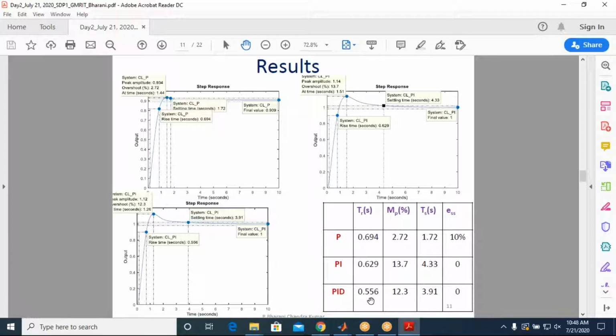When you use the integral action, it sometimes saturates. It gives saturation in the control gain or in the system's response as well. To avoid that saturation, we generally use the anti wind up controller. So anti wind up will avoid the saturation. In practical cases, saturation plays a very crucial role because you cannot change the control gains as much as you want. Practically, there is some limitation.